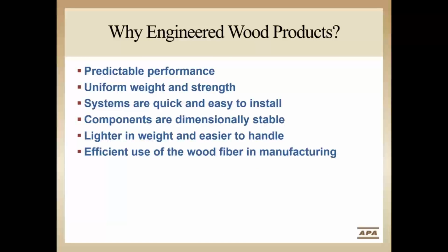So why engineered wood products? Well, again, predictable performance, uniform weight and strength, the systems are quick and easy to install, the components are dimensionally stable, they're lighter in weight and easier to handle, and of course, they make efficient use of the wood fiber in the manufacturing process.